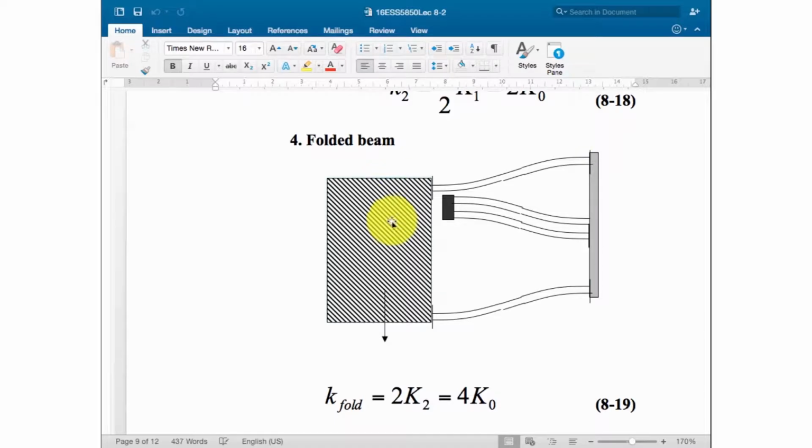So let's talk about only one side of the actuator. Actually, we have all these springs on both sides. On the other side, we also have another set. That means the final spring will become even harder because we have another set to share the force. So each crab leg will share only 1/4 of the force.